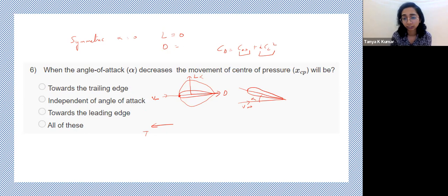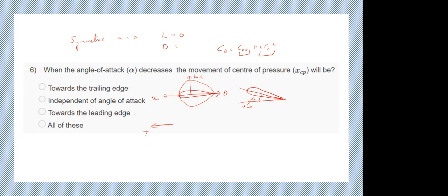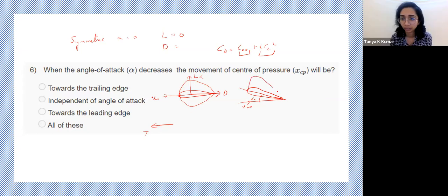Or can someone tell me how the pressure distribution about this airfoil will be at a positive angle of attack? The flow will accelerate above the aerofoil, but will also separate early. On the bottom, there will be positive, high pressure. Yeah, so here there will be something like this. This will be negative and this will be positive. He's right. Positive below and negative above.